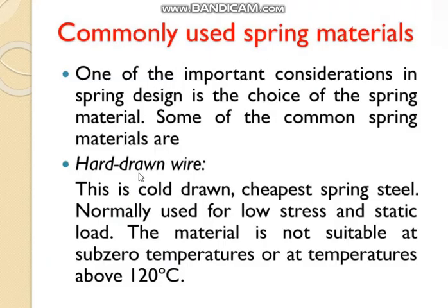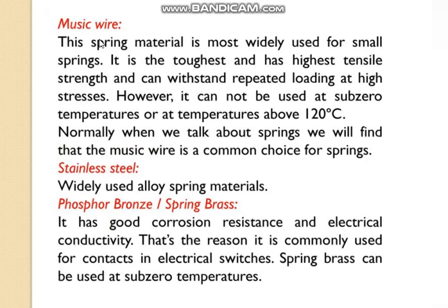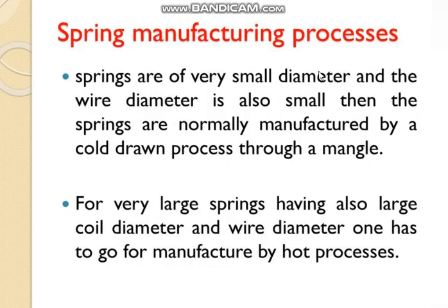Here are some other materials, spring materials: hard drawn wire, oil tempered wire, chrome vanadium wire, chrome silicon wire, music wire, stainless steel wire, phosphor bronze, spring brass. These are the materials which can be used. Even stainless steels and other things also can be used.